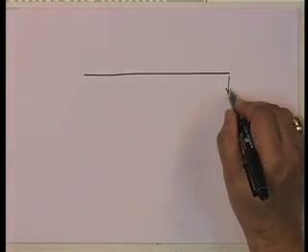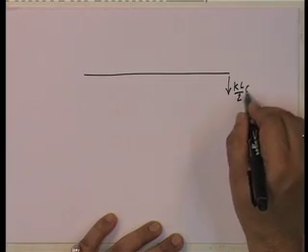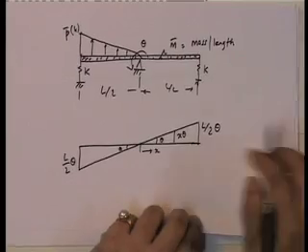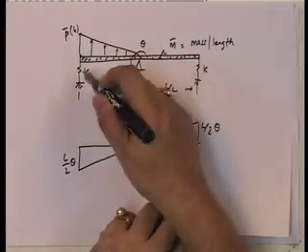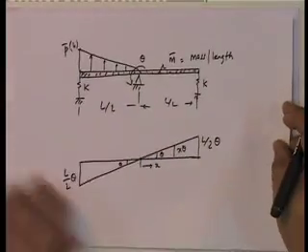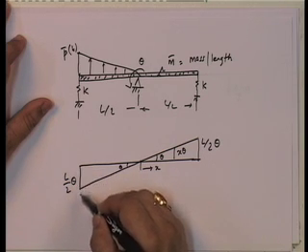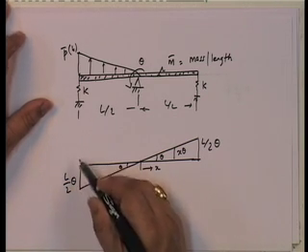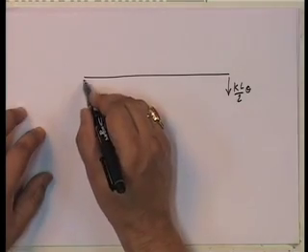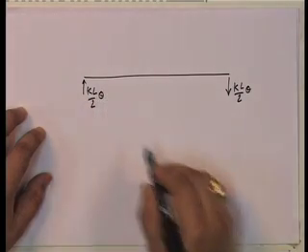So, the force is going to be here, and this force is going to be equal to k L by 2 theta. Note that I have put both of them as identical springs, k k. Here this spring is being subjected to displacement in this direction, so it is going to oppose it. So, this force is going to be equal to k L by 2 theta.